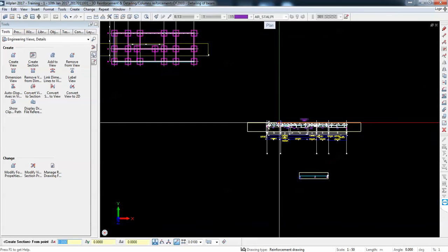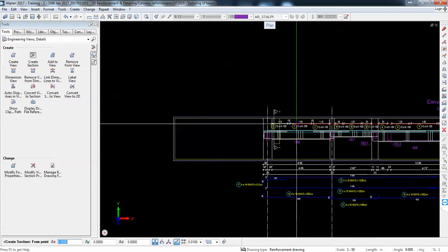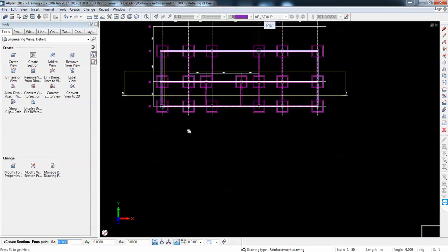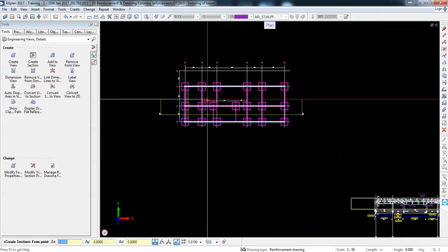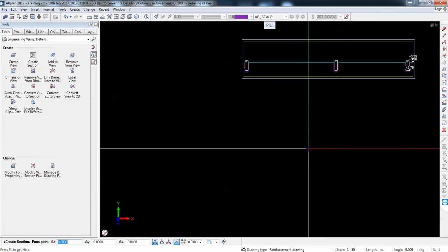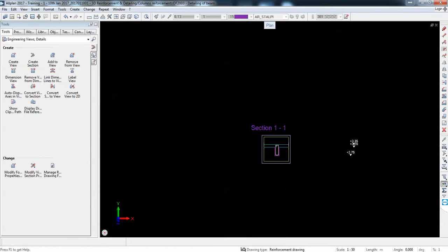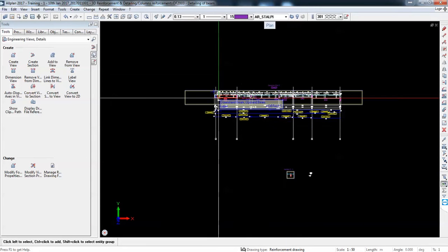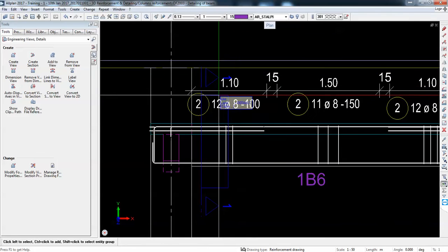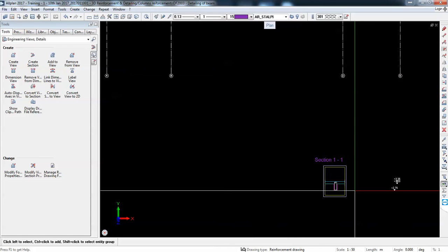Why does this happen? Because when I create an associative view, it marks the entire view as big as the slab. Now I'm looking from left to right in elevation 2. So if I'm here on the left and look from left to right, I can see the middle. So I need the middle one. This is the one relevant. If I am not sure, I pick the correct one. It's enough to select here, and if it goes red, it means I selected the correct beam. So here is a representation. If I need to do any modification regarding depth, everything is the way I've shown.